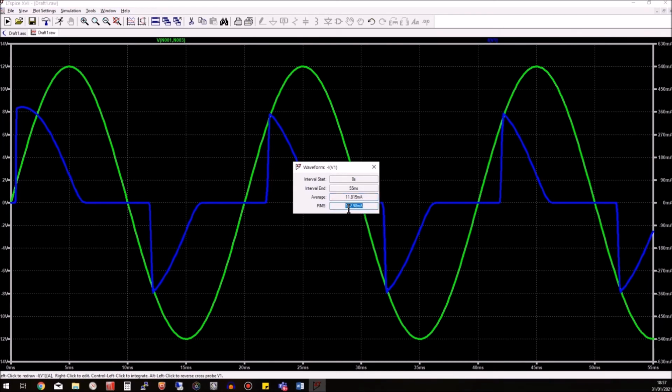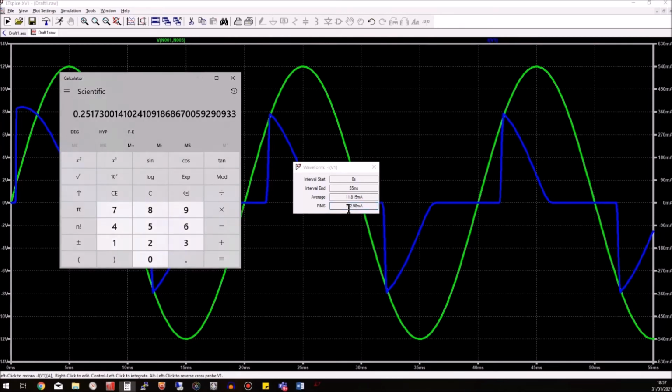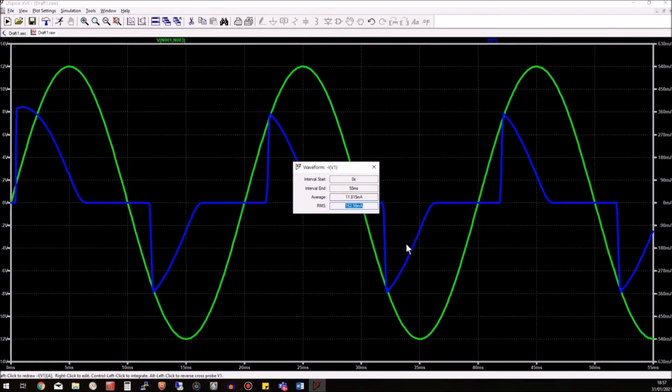It's a lower value, not what I just calculated using the shortcut. The reason for that is because the shortcut assumes that the waveform, being purely sinusoidal, occupies all of the area underneath this curve. So if there's a peak of some amount, then all of this area underneath it has to be filled under the waveform. Here, with the blue waveform, that's not the case.